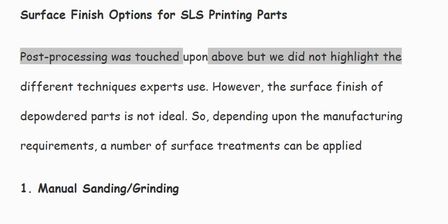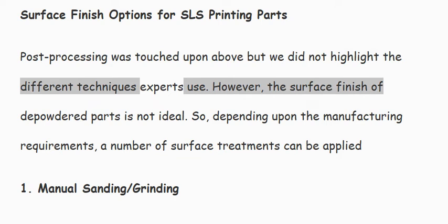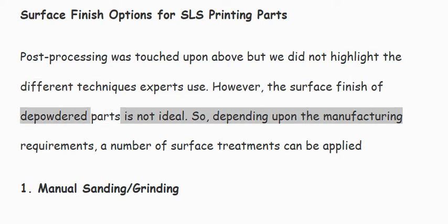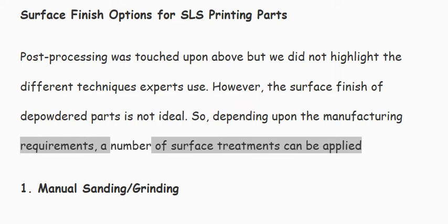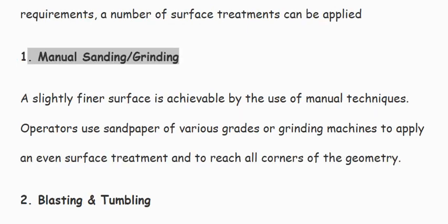Post-processing was touched upon above, but we did not highlight the different techniques experts use. However, the surface finish of depowdered parts is not ideal. So, depending upon the manufacturing requirements, a number of surface treatments can be applied. 1. Manual sanding/grinding.